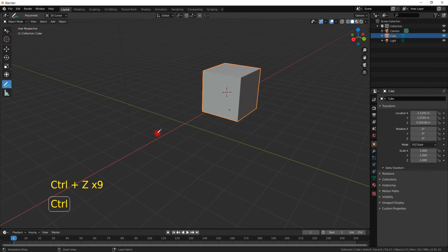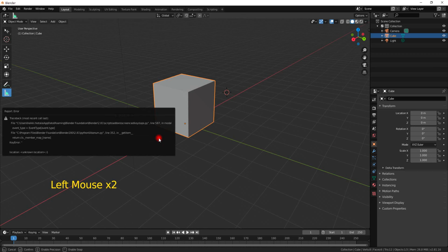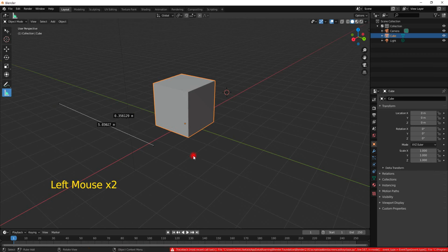And the last one here in the object mode menu is measure. Now, measure is nice because you can just click in here and drag like so, and then you can grab that end and snap to a corner, for example. And this way you can see that if you have a cube that is 2 by 2 by 2, the diagonal length of this line here is 2.8 meters, which is actually 2 times the square root of 2, as you would understand from your geometry lessons.